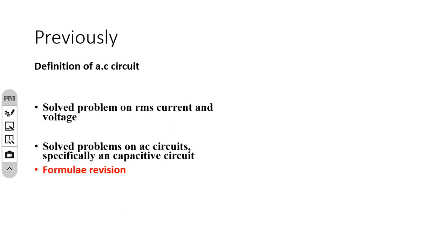The revision for the expression we used initially, you can see here equation 4. We are not starting from equation 1 because it is just a continuation. So this was equation 4 in our previous class. You see the root mean square value of current is equal to peak value of current all over root 2. So if I divide 1 by root 2, then I will obtain 0.7071.